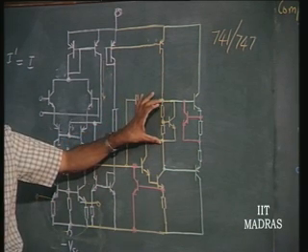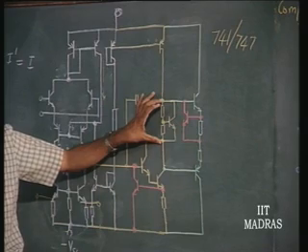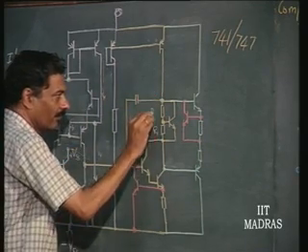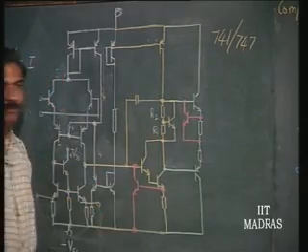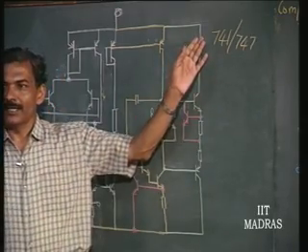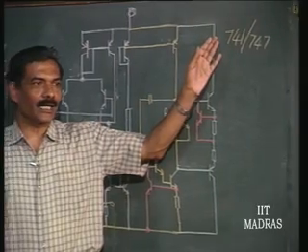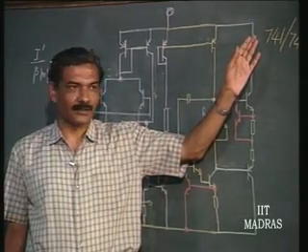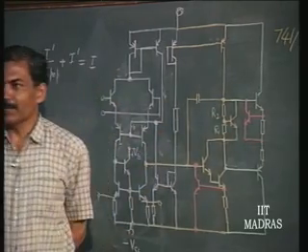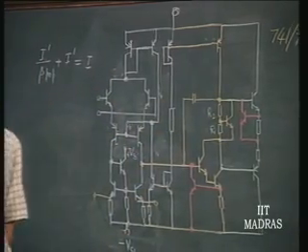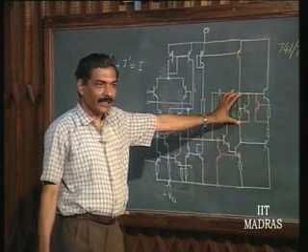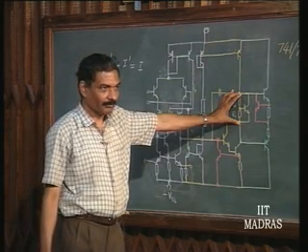Not current mirror, this is voltage reference, which can generate a voltage which is nothing but V gamma into 1 plus R2 over R1, necessary for biasing a class B in class AB mode of operation. Okay. So, this R2 over R1 is made less than 1, so that the voltage between these two is equivalent to slightly less than 2 diode drop.